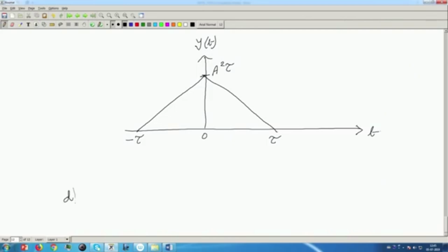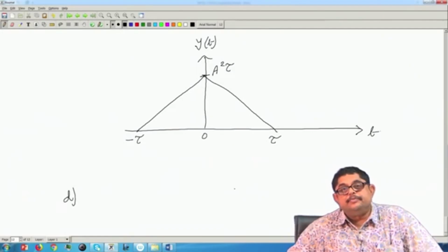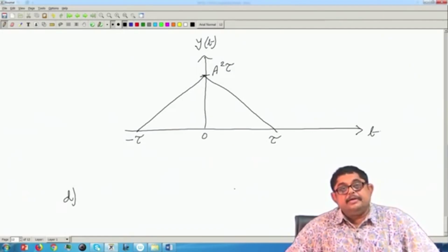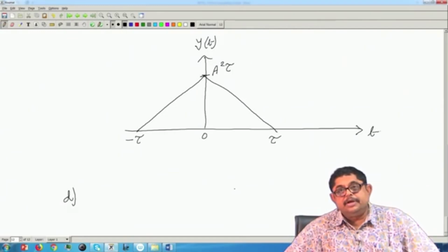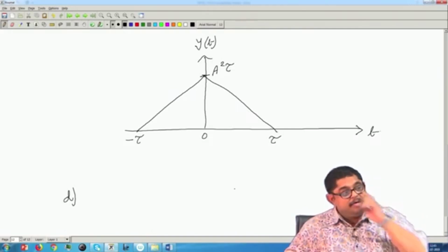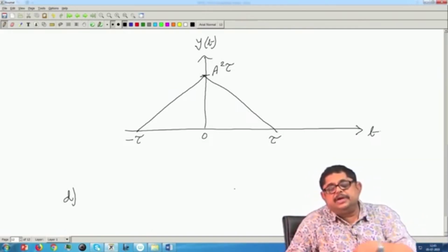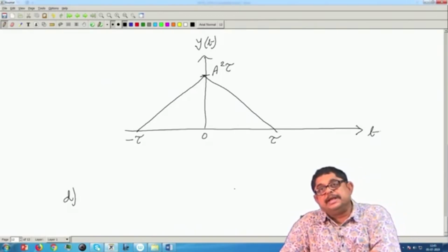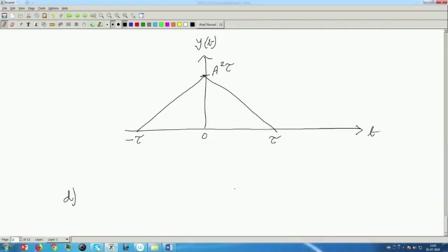Now, the next part is that negative frequency. You know that the negative frequency concept started from Fourier, because we are taking transfer functions etc., those are Fourier transforms. For mathematical soundness, because Fourier tried to break a real signal into its eigen components, that is why the complex things came, and that also introduced this negative frequency concept. This negative frequency concept does not have physical meaning, but for mathematical reality it is there.